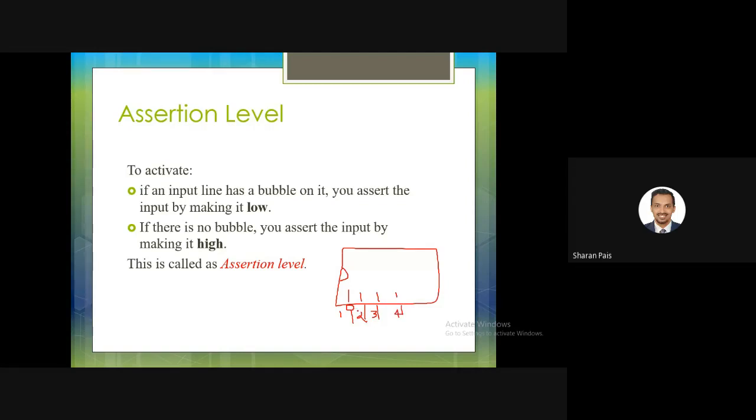For some of the pins in the pin diagram, they mark a bubble. It tells you that whatever signal you want to give, give it reversed, because inside I am negating it. So if you want to give high, for 1, don't give high, give low. Reverse.